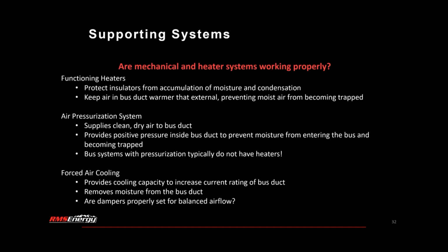becoming trapped. And one note, with these two systems, if you have an air pressurization system, you likely don't have heaters. So if you begin to see issues with maybe your seal-off bushings are failing or your gaskets are failing and you're not able to maintain pressure on that bus system any longer, you don't have a backup line of protection like you do with heaters. So it's important to maintain those systems and try to address issues with your